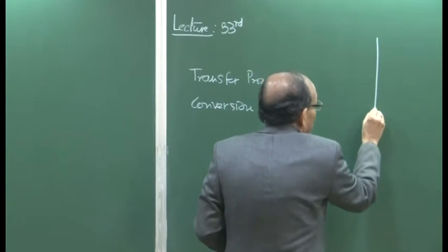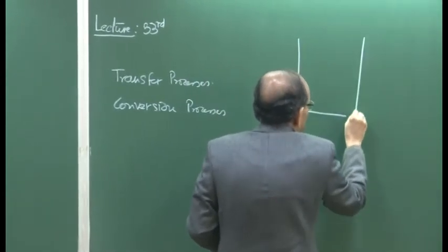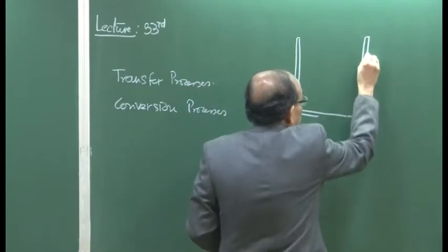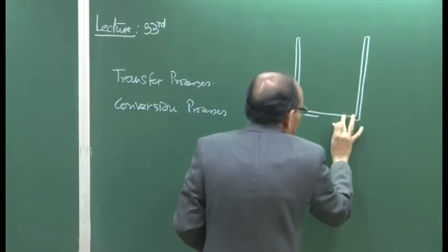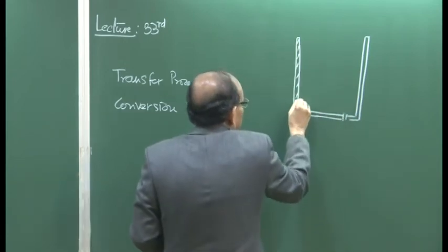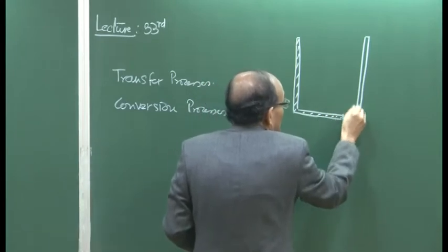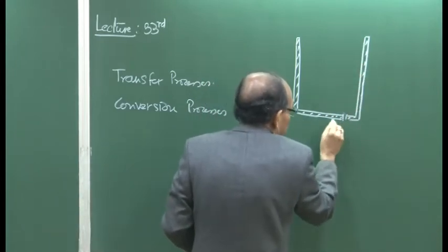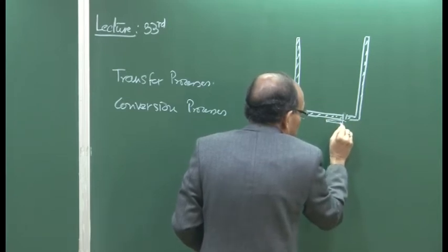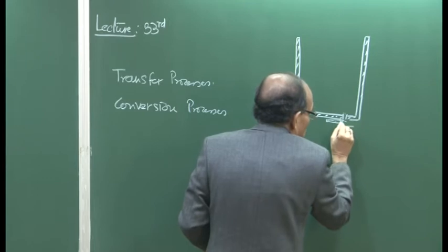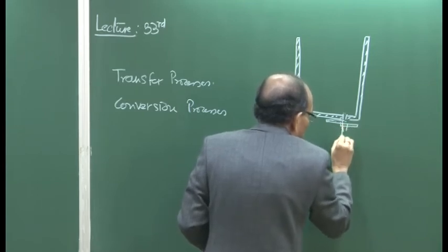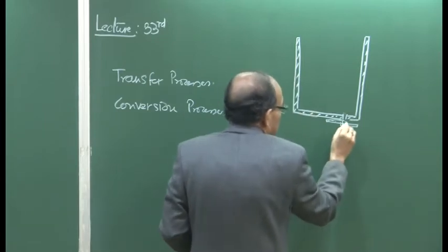how molten steel is transferred from a ladle through. So, we have a ladle well here, and this is the refractory lined ladle, and I showed you that we have a slide gate plate here. And then we have a collector nozzle onto which a ladle shroud is mounted.